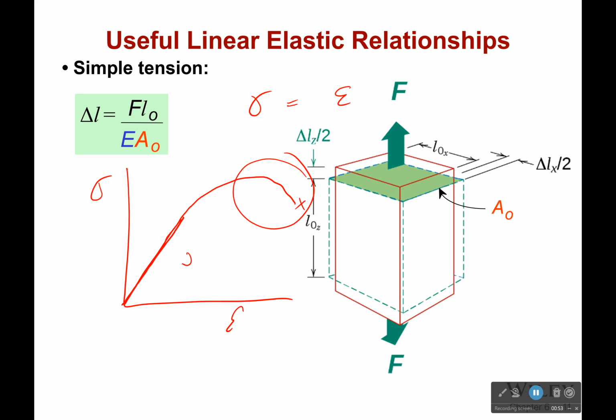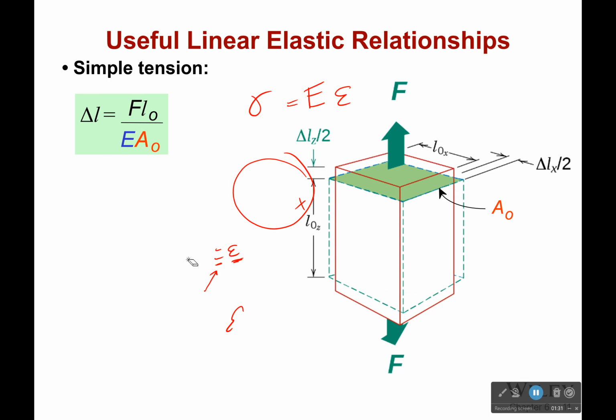And in this section, there's a nice little equation which is called Hooke's law, because our stress is equal to our modulus of elasticity times strain. And this is species specific. We're going to get into where that comes from soon. What you see is that in this section, the amount of stress I apply is going to cause some proportional strain. So all the equations we're about to talk about only work in this nice linear section here, which is called the elastic region. Beyond that, things get wonky, we can't use this anymore. So stress is equal to modulus of elasticity times strain. Okay, with that explained, now let's jump right into this.